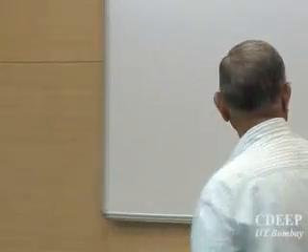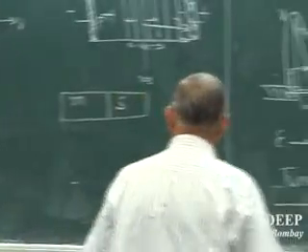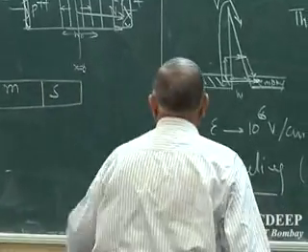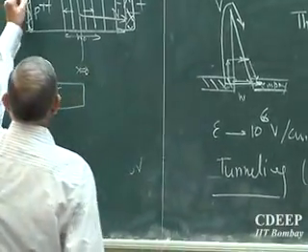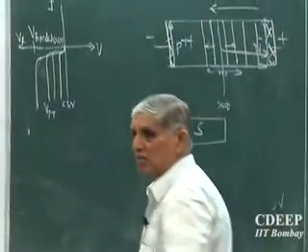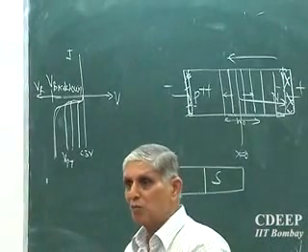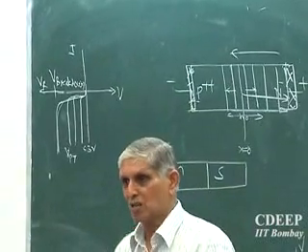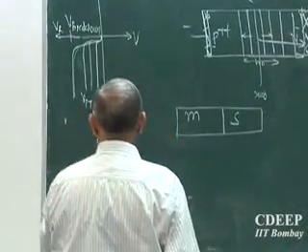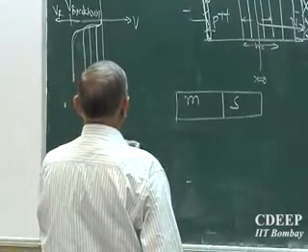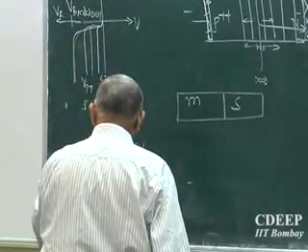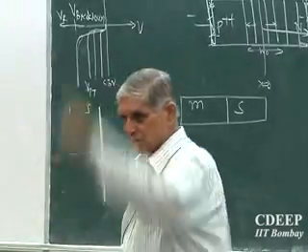Okay. Now what is it? That's last part of this junction. So what is ideal ohmic contact? We say ohmic contact means what? Whatever carriers are coming here without getting modification goes to the external world. So essentially good ohmic contact should have ideally this characteristics.